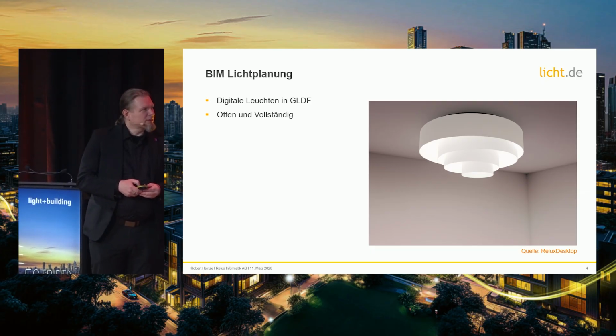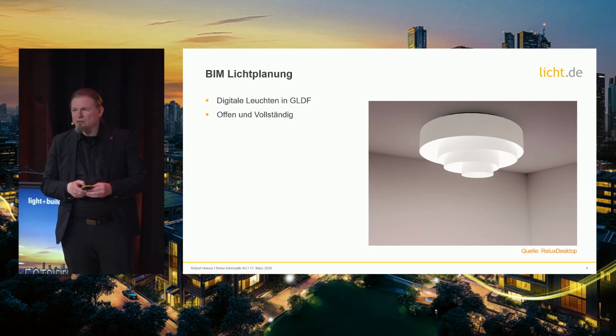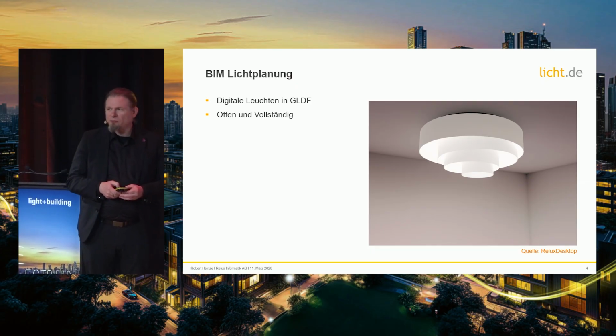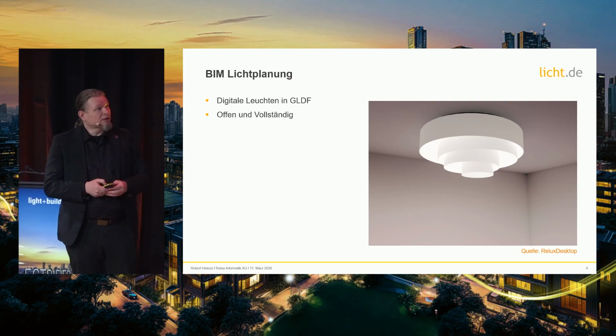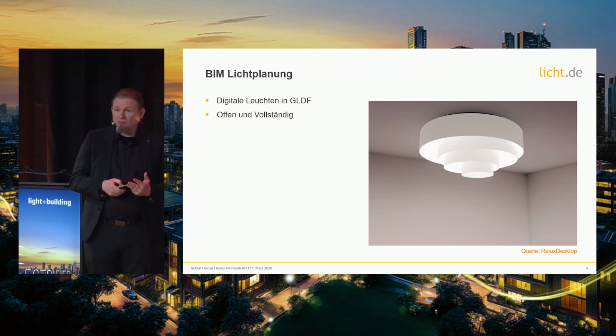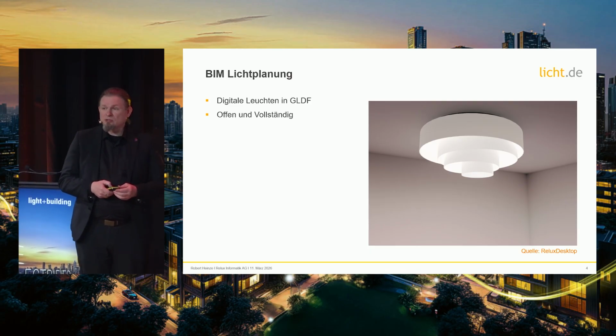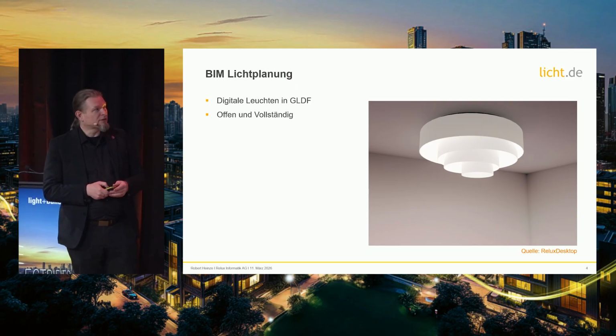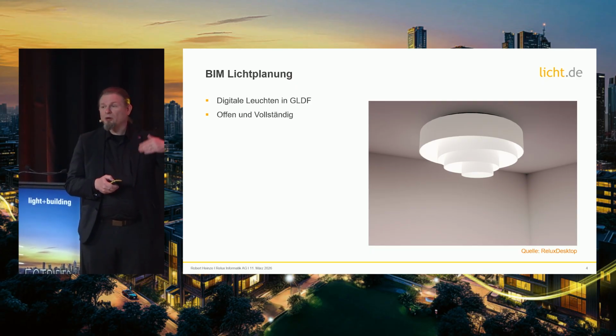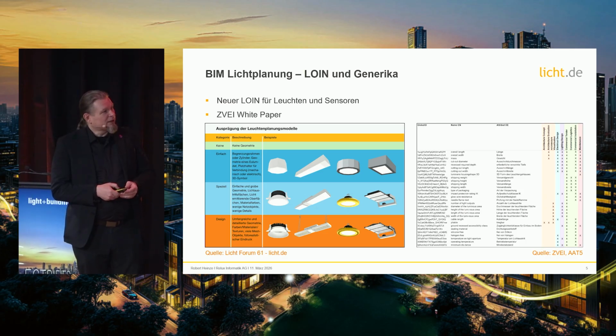Now, BIM light planning. There are a number of digital luminaires. We have a new format for that called GLDF. I just recommend this to all the manufacturers to take a look at this format and to publish their data on their luminaires, which gives us an open and complete standard to describe luminaires with the geometry and the light exit and so on. Which really completely covers a luminaire digitally. This should be used, GLDF. It is publicly available, and it goes across different software programs.